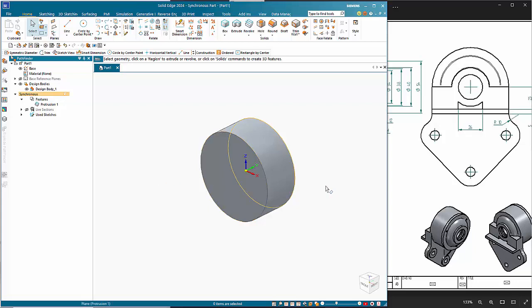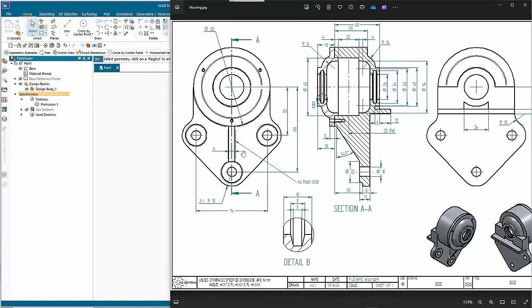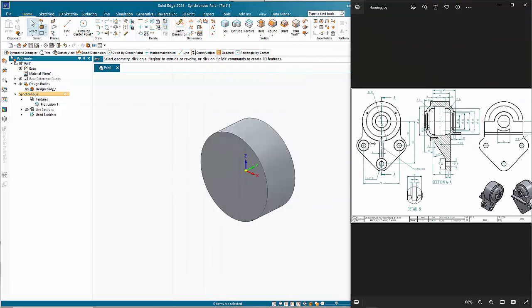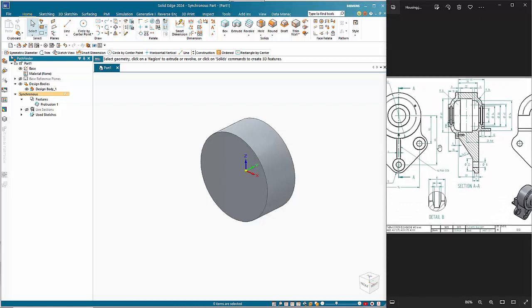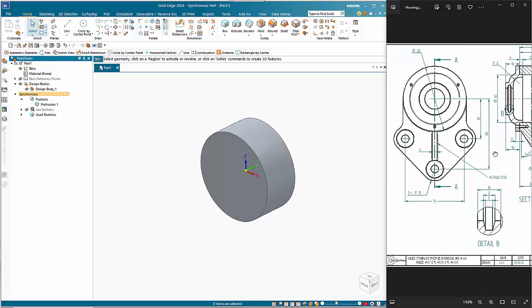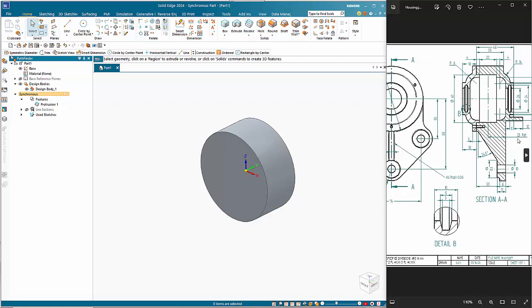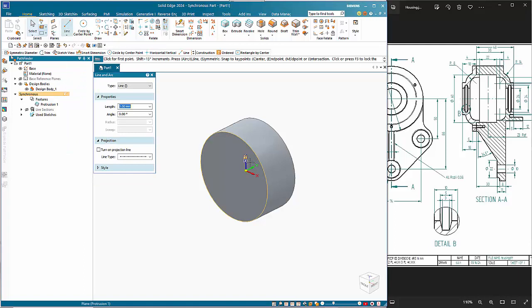So from here, I want to create this sort of profile here, and we'll be able to see if I squash this down. We're sort of looking at this area here, so it's 76 equidistant, 88 down for this hole here, and 50 down for these. And positionally, this is going to be 23 off that center line, so off the coordinate system that we've created here. So if I just start by drawing it over the top of that plane, just hover over, you get the right mouse click option, and we want to choose this base reference plane.